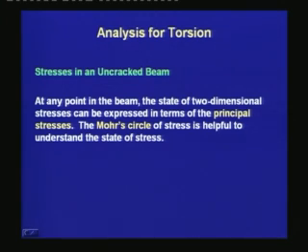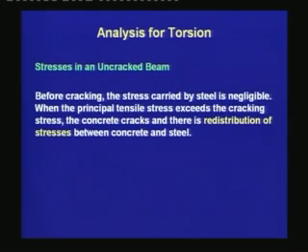The Mohr circle of stress is helpful to understand the state of stress. Before cracking, the stress carried by steel is negligible. When the principal tensile stress exceeds the cracking stress, the concrete cracks and there is redistribution of stresses between concrete and steel.